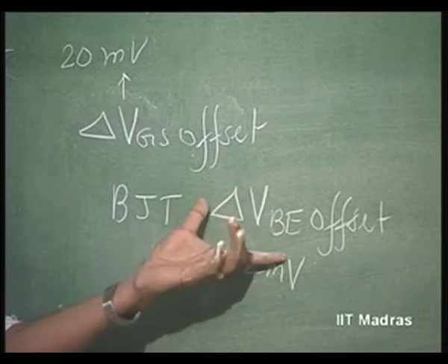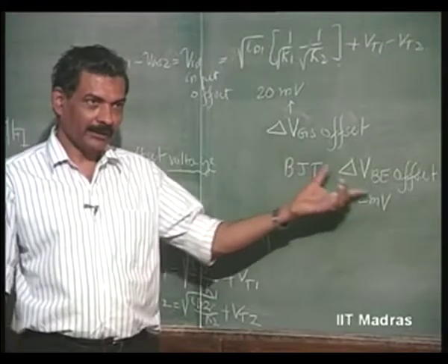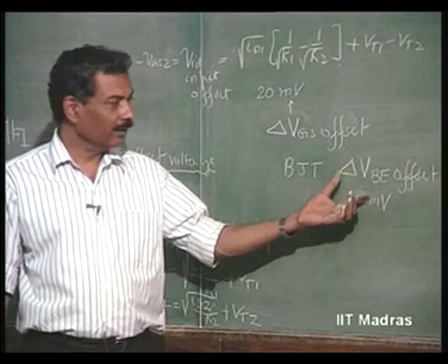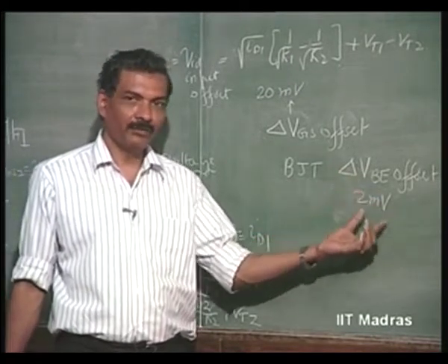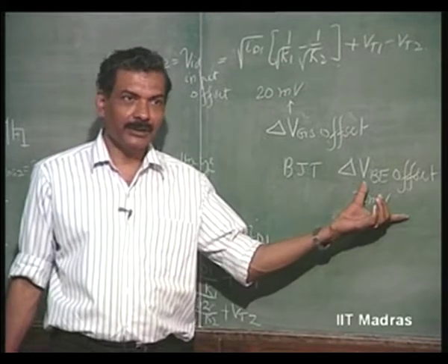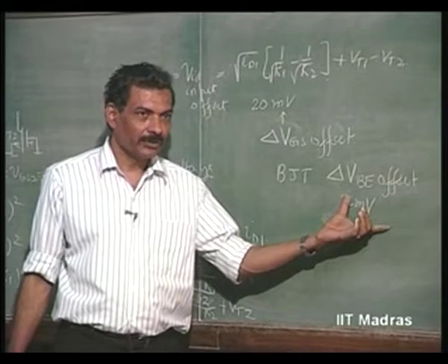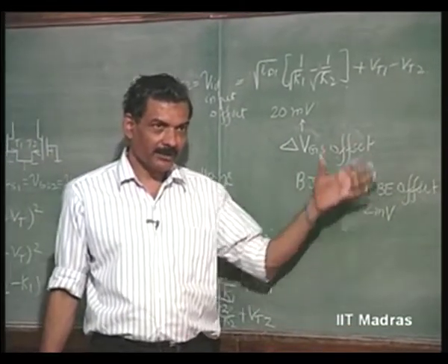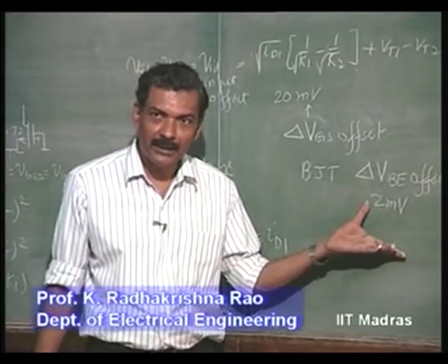And also in this I said, if you go for higher input impedance by pairing Darlington transistors as differential pairs, then the uncertainty here will go to double. Instead of 2 millivolts it will become 4. If you use 3 such transistors, it will become 6 millivolts. Even though the beta is progressively increasing and the base current is progressively decreasing, or input impedance is progressively increasing.